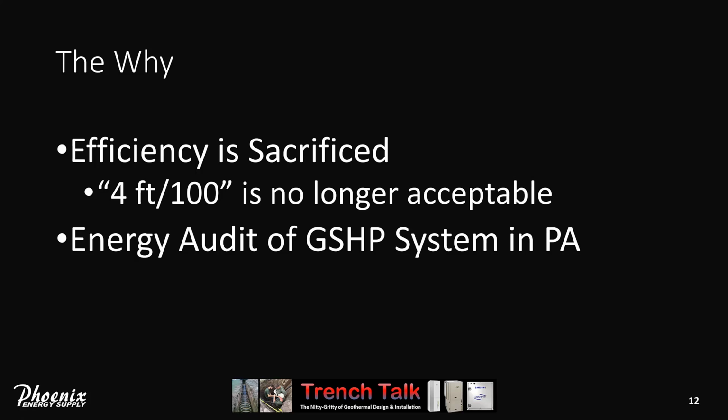And it's because the engineer who designed it did not want to use two-way valves at every heat pump. And the pump was set up to run at full speed, 24 hours a day, 7 days a week, 365 days a year. And it was outrageous.